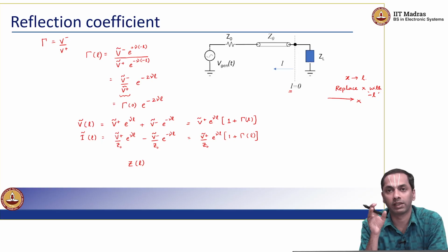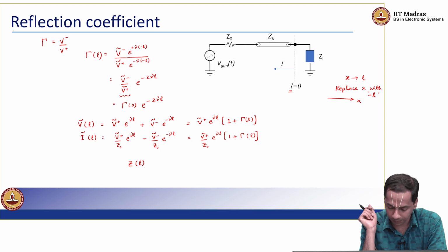And if we call that the impedance at that particular location, V by I, we are noticing that we are getting different impedances at different points along the transmission line, right? Nevertheless, it's a periodic appearance, right? But we do notice that there is a change in the net impedance.